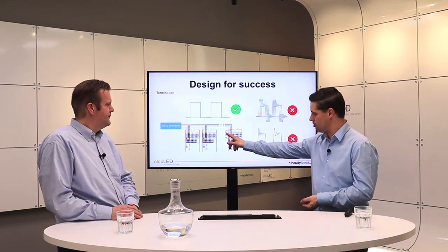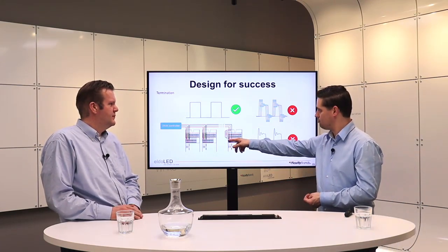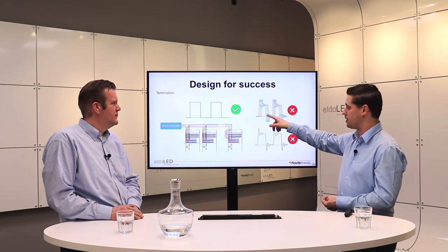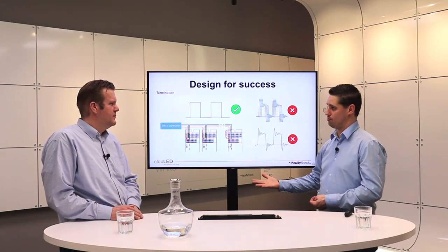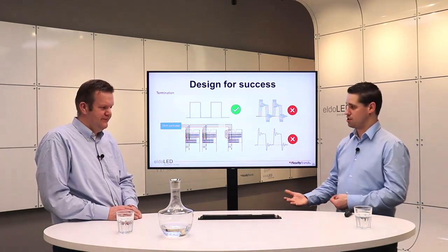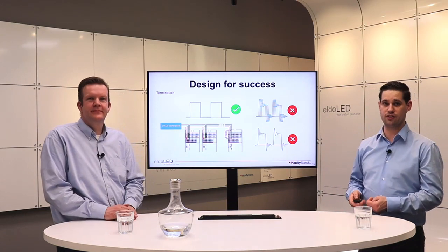So that resistor, however small, is the difference between having a clean signal and having echoes and reflections on the line because the line is not terminated properly. So a 10-cent component can make the difference. A 10-cent component will make the difference in the reliability of your installation, indeed.